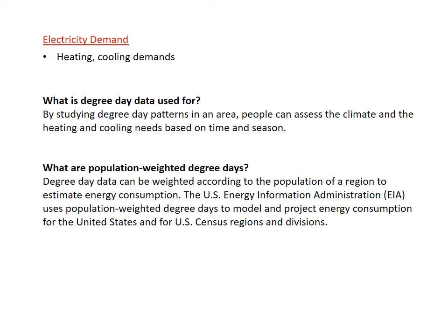You could come up with a linear regression that would incorporate heating degree days and maybe some other stuff as well. So you take advantage of the known relationship between heating degree days and electricity demand. And because you're accounting for degree days separately, right, you can actually create a linear regression, and you don't have to worry about this nonlinear relationship between temperature and electricity demand.